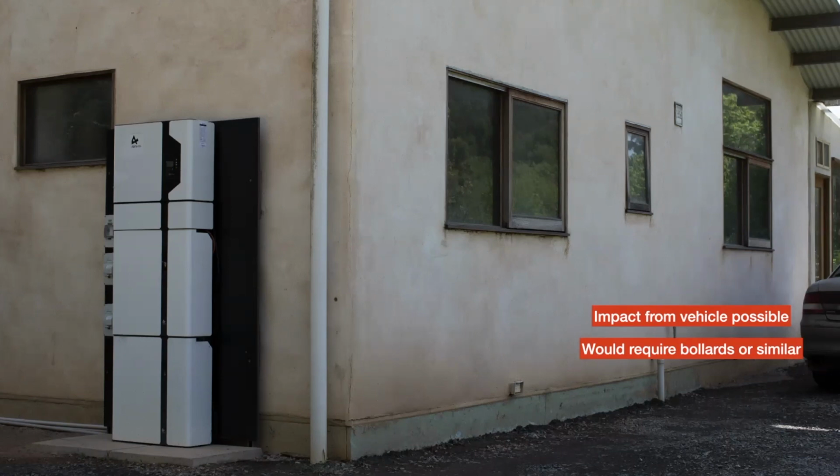This driveway is not wide enough to put bollards in. I wouldn't be able to get the car in. But the bigger problem is there's so many windows. Remember, I have to be more than 600 mils horizontally from a window and more than 900 mils below. So there's nowhere on that eastern wall that I could put a battery system.